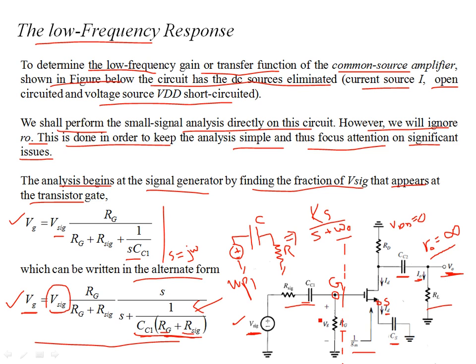However, the internal capacitances are to be considered open circuit at low frequency, because the capacitances between gate and drain and gate and source, or the junction capacitances, are on the order of picofarads. They are small, and their capacitive reactance can therefore be considered an open circuit. So we are not considering the internal capacitances of the MOSFETs, just the external capacitances, which introduce a frequency dependent gain transfer function between the output and the signal at low frequencies. That's all.